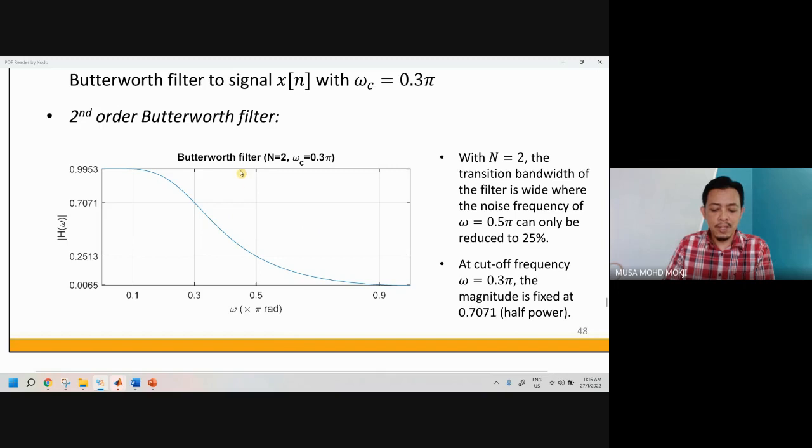That's why we start everything by finding the cutoff frequency, maybe the stop band edge frequency, the pass band edge frequency, the transition bandwidth, the ripple, which is everything in the spectrum. We are looking at the spectrum to design a filter. So why is that? Hopefully that is your question.